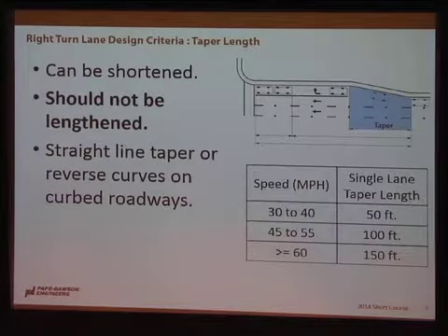Now, taper length is that other component. I would say you can always shorten your taper length, but you probably don't want to lengthen it too much. I forget where I was driving the other day, but I was in a location where there was just a massive expanse of asphalt because there was a super long taper. In that situation, drivers don't seem to know whose lane they're in. So it's better to keep that a little shorter, in my opinion.